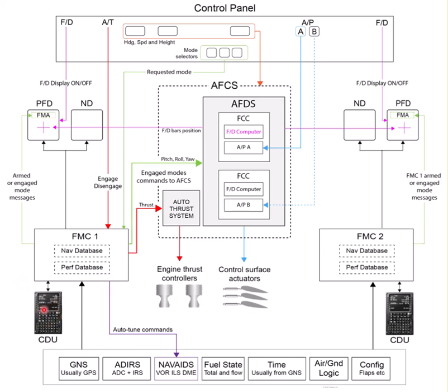So when you program the CDU, you're telling the FMC how you want to achieve what you're after, how you want to fly your route, and you're giving the systems information that they're going to need to either guide you using the flight director, because that is still possible, although not usual of course, but that information will also go into the AFDS in pitch and roll mainly, and whatever the LNAV and VNAV route profiles tell the Autopilot to do and the auto throttle to do, then they will do that.